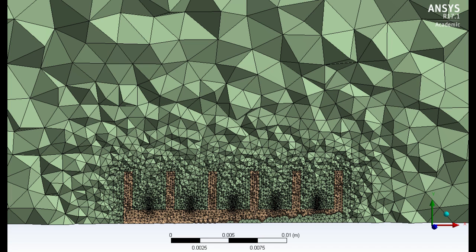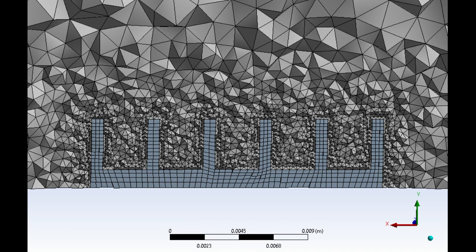In order to get a measure of the effective heat transfer, the heat sink was set to a temperature of 40 degrees Celsius, which is a warm running chip but below the typical maximum operating temperature of electronic components, around 85 degrees Celsius. The temperature of the air at the outflow boundary was used to see if there was a significant difference between the two heat sink geometries. The enclosure boundary conditions were a no-slip condition and a no-heat flux boundary condition.